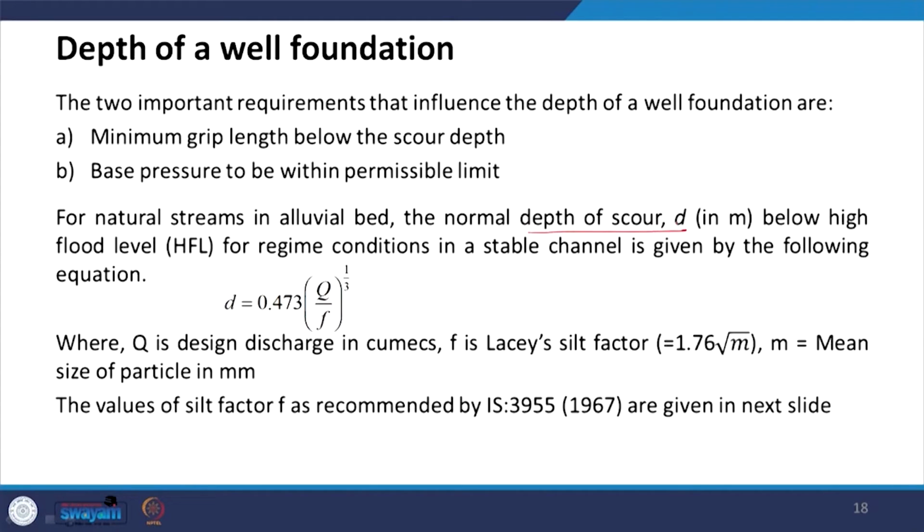This is not the depth of well foundation, you are finding depth of scour, and the depth of scour depends on two factors. One is the flow Q, which is the design discharge in cumecs. That is the one factor, and the second factor: when this water is passing through some granular soils or some kind of soil, what are the sizes of the particles through which it is passing?